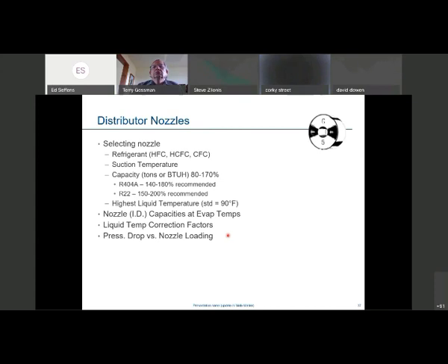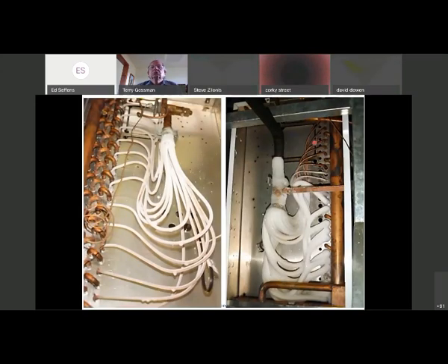So instead of having, again, a 10-ton expansion valve on a system, you could have a 15-ton expansion valve on a system, and you could overfeed and possibly slug back during low load conditions and stuff. So that's important. Again, and then the pressure drop that's required across the nozzle itself. Again, a lot of this information is available in the catalogs.